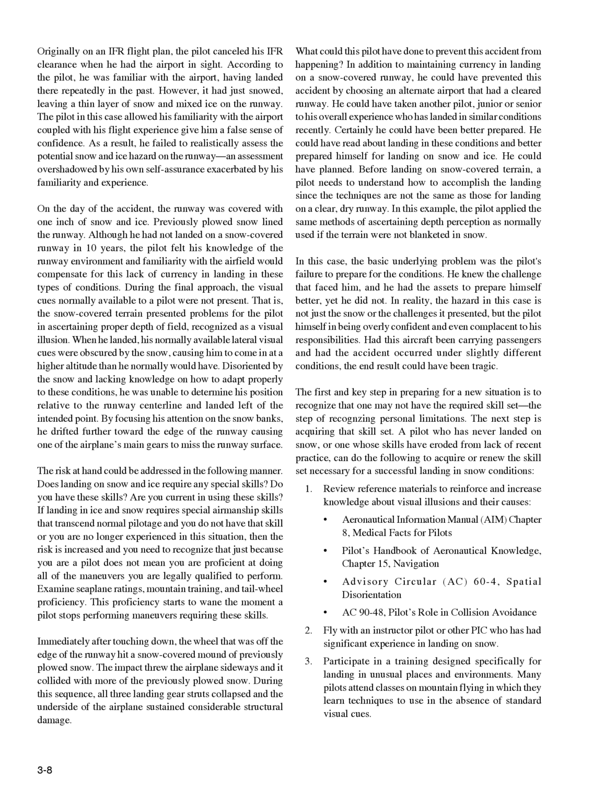The risk at hand could be addressed in the following manner. Does landing on snow and ice require any special skills? Do you have these skills? Are you current in using these skills? If landing in ice and snow requires special airmanship skills that transcend normal pilotage, and you do not have that skill or you are no longer experienced in this situation, then the risk is increased and you need to recognize that just because you are a pilot does not mean you are proficient at doing all of the maneuvers you're legally qualified to perform. Examine seaplane ratings, mountain training, and tailwheel proficiency. This proficiency starts to wane the moment a pilot stops performing maneuvers requiring these skills.